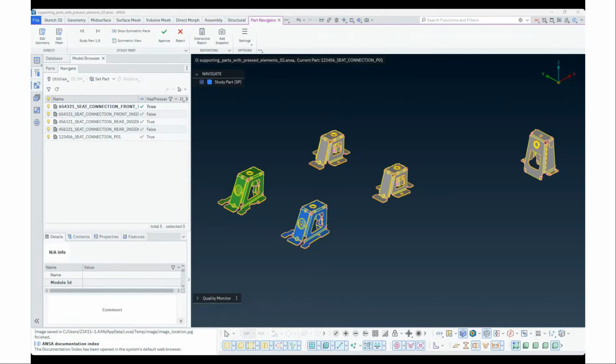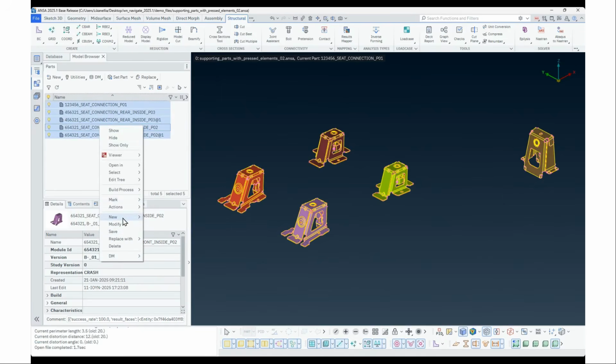After batch meshing or geometry conversion, post-processing involves critical verification steps such as checking mesh quality, confirming part names and properties, verifying thicknesses, materials, and overall meshing success. To support this, ANSA provides a contextual navigation ribbon, quick access to relevant functions, and efficient interaction tools like accept/reject actions to streamline review. I start by selecting the parts.